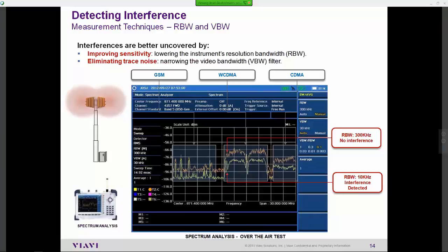It's not to say you can't do it, and it's not to say the impact may not be minimal, but I can give you one example where they were deploying a DAS system and decided to omit GSM coverage in that DAS. This adjacent signal became a major problem because a lot of the people inside the assembly hall had switched their phones to GSM-only mode, which meant their phones were literally screaming to try to get out of the building to a GSM macro site.